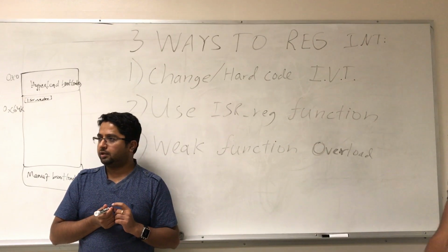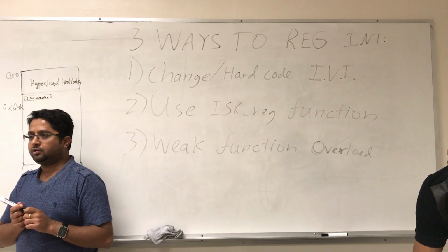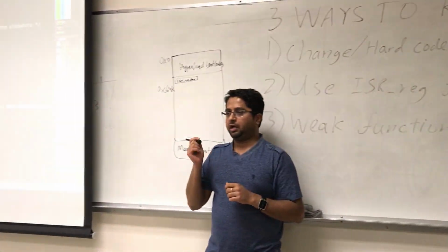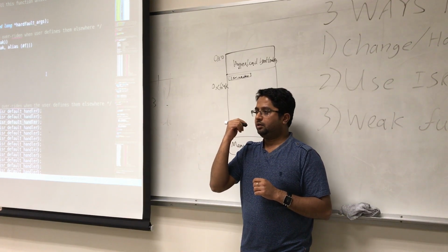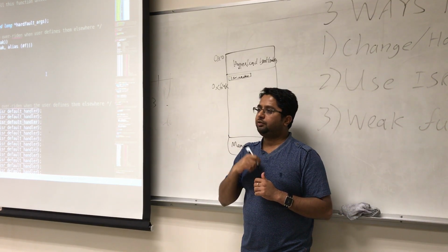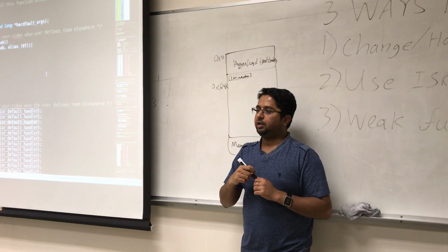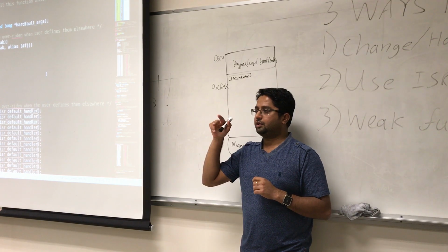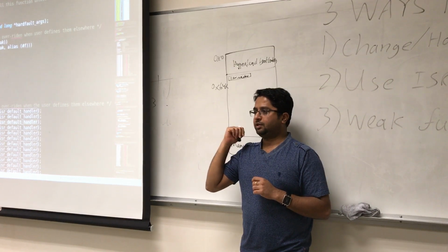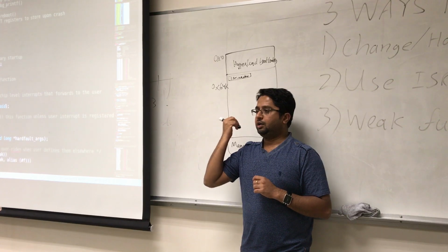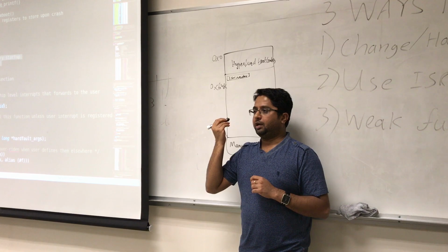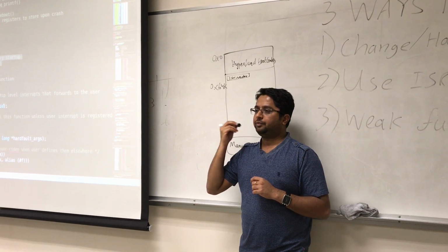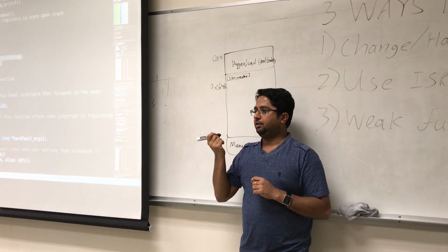Yes, one other thing is, when you are writing the source code for the interrupt handler in a .c file, you can just use the handler name and then write your function definition. But if you're using this in C++, then you will need to use a keyword called extern "C", which tells the compiler to treat this as C code and not do function name mangling.